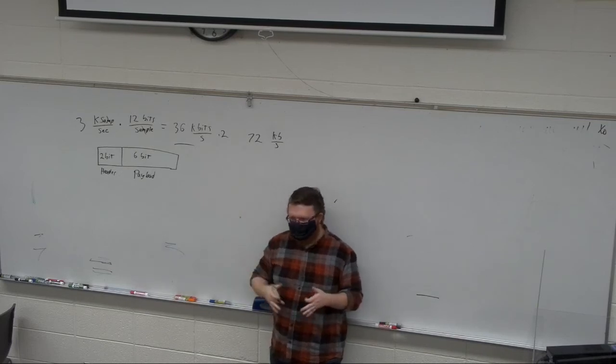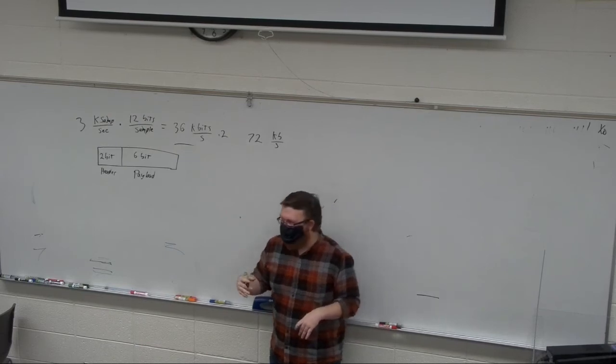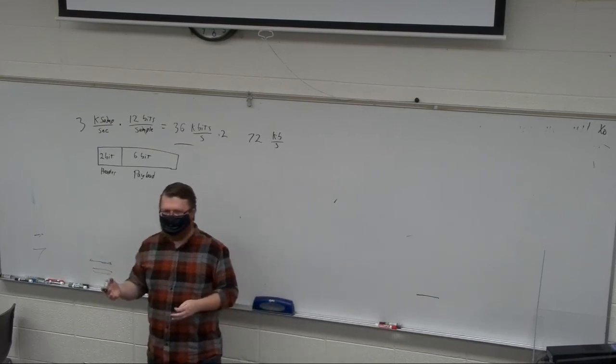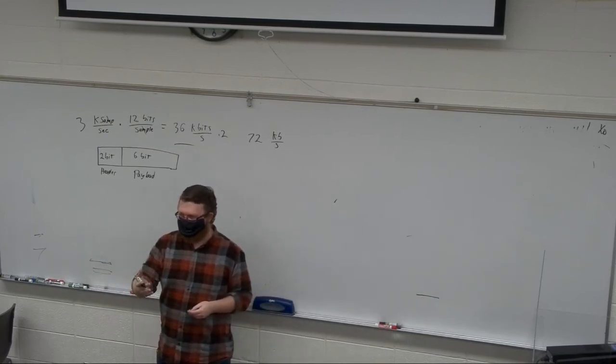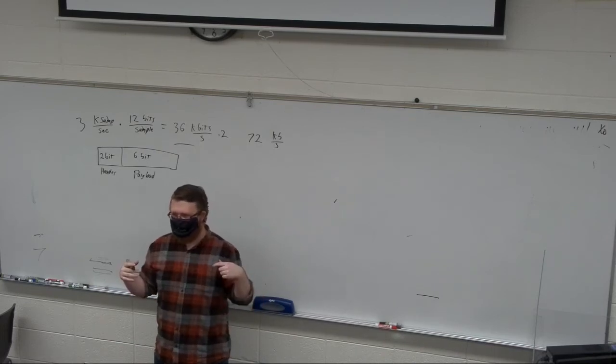The longer we record, the more that fills up. So you're going to need to calculate how big your FIFO needs to be in order to record for X amount of time. And I'll post all of that in the lab. That calculation, just as a hint, is just going to be looking at how fast do I write new data, how fast do I read data, therefore how fast is it going to be filling up as I transmit.